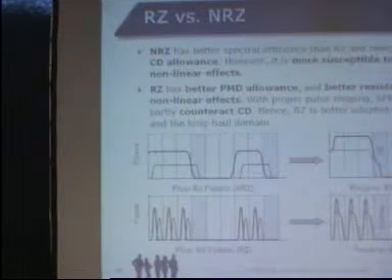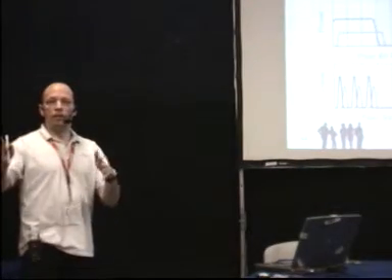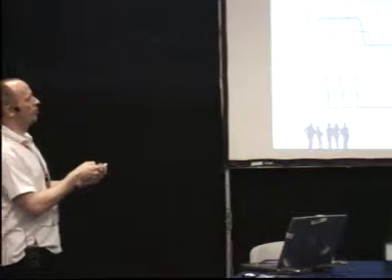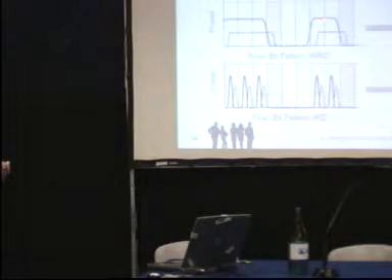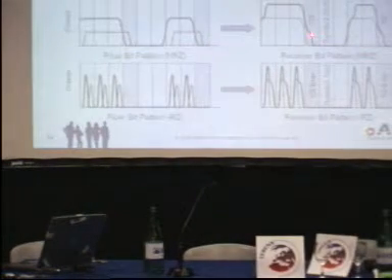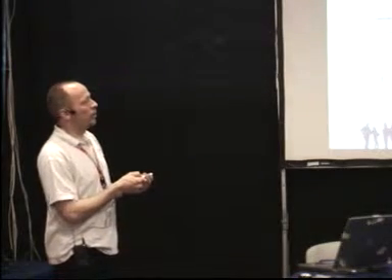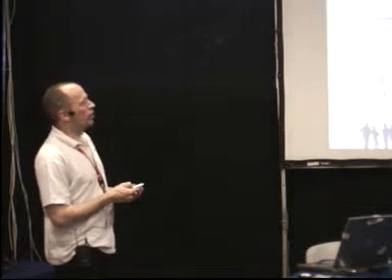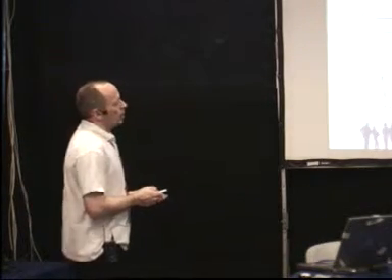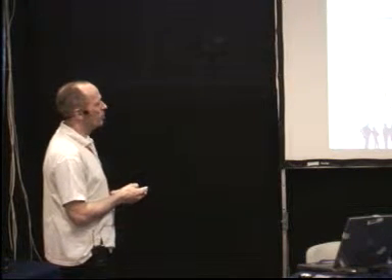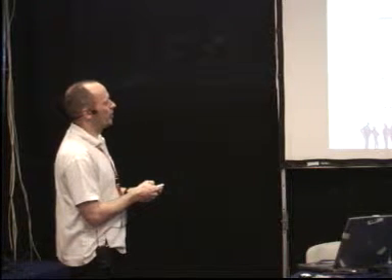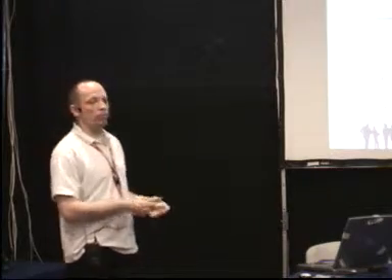Polarization mode dispersion mainly leads to something like two-way transmission, or at the receive end an additional echo being received, and obviously this echo overlaps with the other mode, and hence something like this here can occur. By the overlap of the two modes, the combined signal can leak into adjacent time slots, which simply causes intersymbol interference or bit errors. With proper return to zero modulation, there's still some space in time left for this dispersion mechanism, and hence there might be no intersymbol interference. This looks rather simple, but it is really the effect behind return to zero.